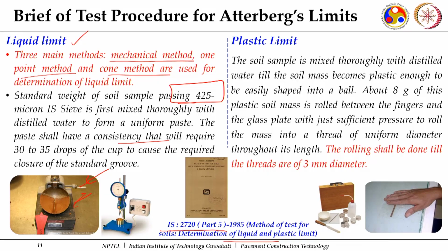If I have more water content, then it can get closed up after, say, 10 blows. If it has a lesser amount of water, then you may have to give 50 blows and it is still not closing down. Normally I prefer it to close down in the range from 15 blows to around 35 blows. So I can initially add some water, see if it is closing down at 15 blows,